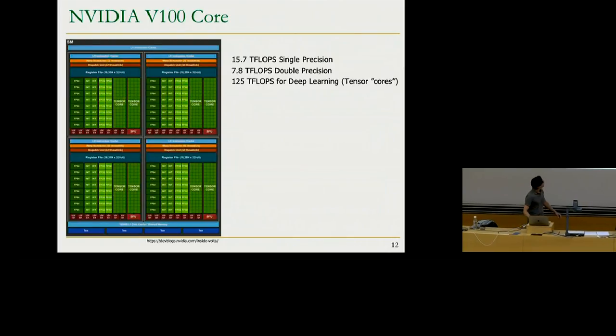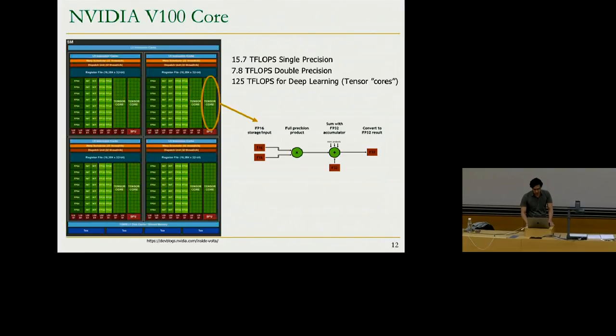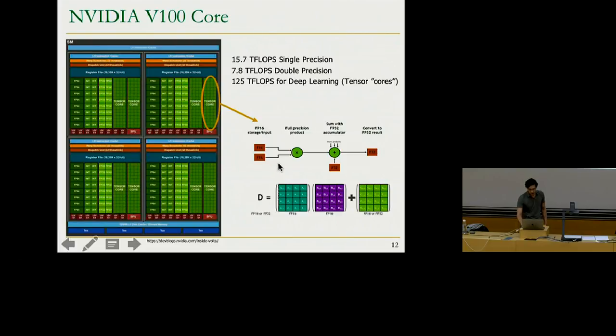units. And then we also have these so-called tensor cores that actually are a kind of specialized functional unit for machine learning. You know that machine learning and deep learning in particular is more and more used in current applications in many different fields nowadays. So that's why they decided to include these functional units. You can take a closer look at this. This is essentially intended to do matrix multiplication. That is an essential operation in current deep learning applications. You can take a closer look here and maybe find more information in this link.